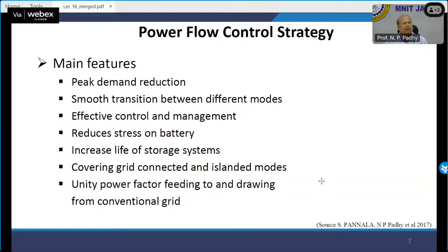So let's say you have a battery. You have to design a battery control strategy. By measuring the SOC, you will decide whether it has to be charged or discharged, considering the other outer conditions. Am I right? So you will measure whether the load is more than generation or less than generation within the microgrid, and see whether the system to which you are connected is suffering at peak, off peak, or islanded. And then you give instruction to your battery what to do. That is what the control strategy is all about.